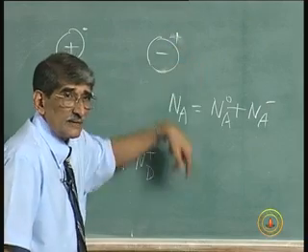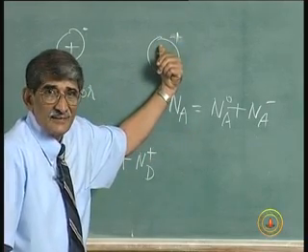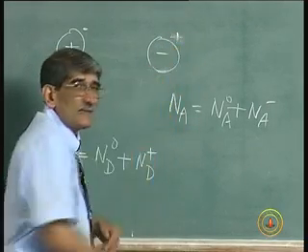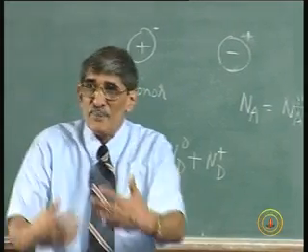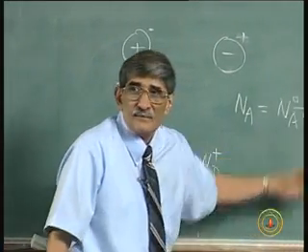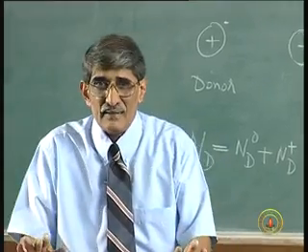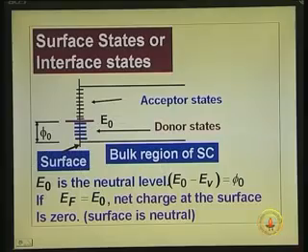You remove from there to there means what? You have brought an electron in there. You bring in one electron, that becomes negatively charged. That is why when you occupy it, it becomes negatively charged. Unoccupied is neutral. So, with that understanding, you have to spend more time thinking about it. But the simple thing to remember is levels below the Fermi level are occupied, and if a donor level is below the Fermi level, it is occupied, and when it is occupied, it is neutral. An acceptor level above the Fermi level is not occupied, okay, and when it is not occupied, it is neutral.